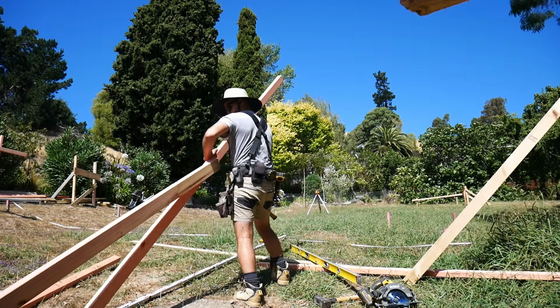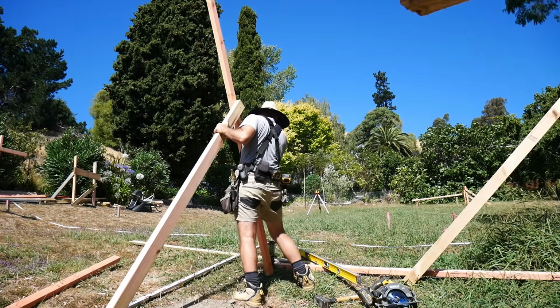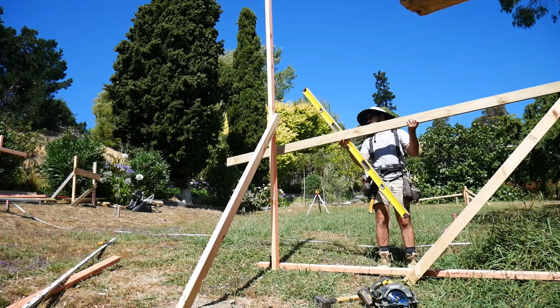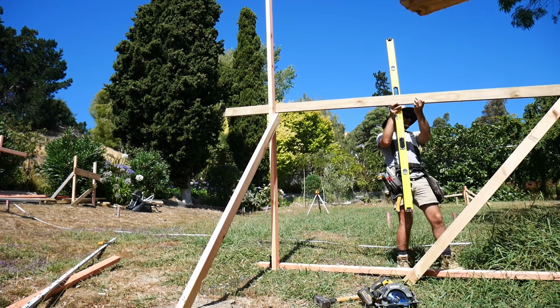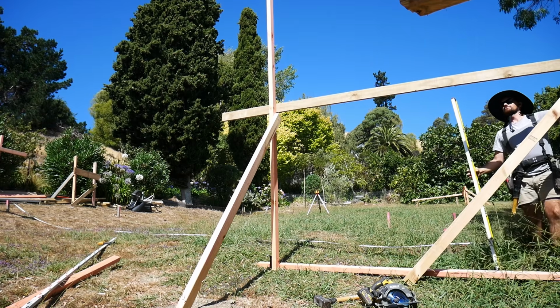The last profile I need to build is the tallest, and it also captures more than one corner. Pre-attaching the braces to the uprights helps when getting started, and then I work my way up from there. I also use a mid-rail on this profile to keep the uprights rigid so they don't bow and buckle.